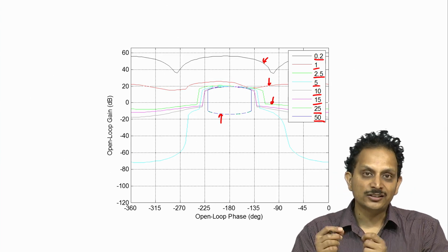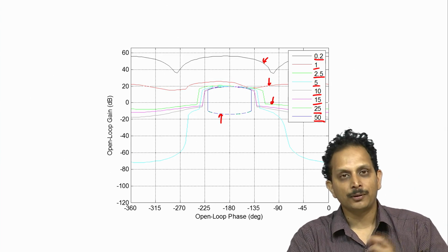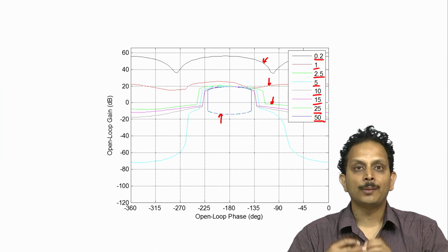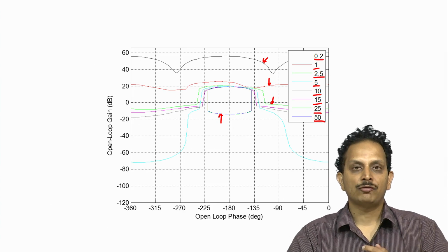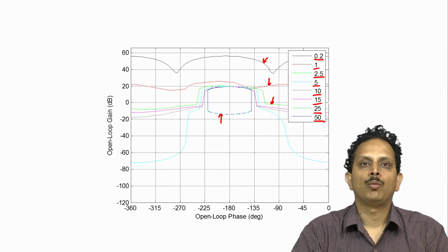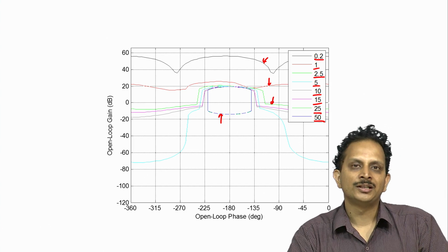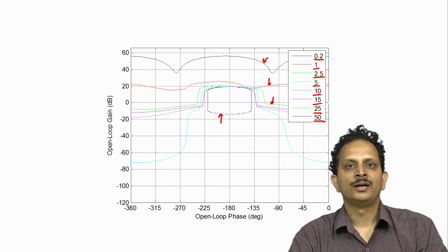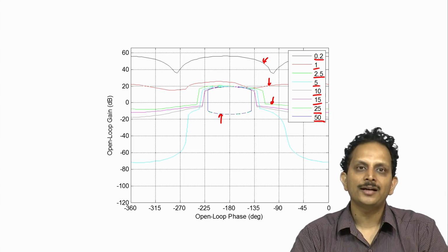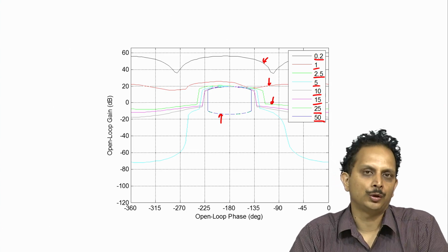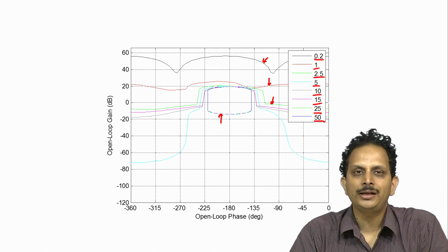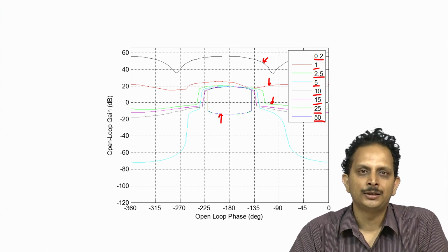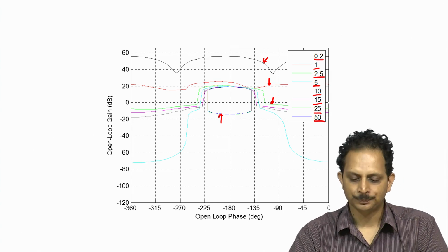If the loop gain is exactly on these bounds, then the performance specifications will be exactly met. On the other hand, if it is above these bounds, then the performance specification will be met better than what is expected, or in other words the variation in the transmission function will be regulated to a magnitude that is less than what we had wanted it to be regulated to, and that would result in a slightly conservative design, which is still acceptable, because we have ended up doing better than what we were asked to do.